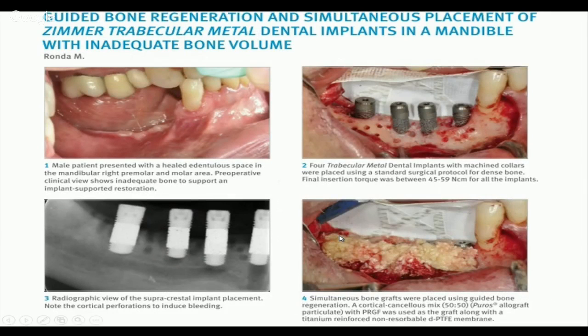the Regenerex. This is one of the examples, again by Zimmer, where they have introduced this kind of dental implant with about 0.5 to 1 millimeter of porous thickness, where porosity is about 70%, and this is more than enough to increase the surface area by about 90%, and eventually gives tissue ingrowth and biological fixation of the implant to the tissue site. And you can see from microCT that there is tissue ingrowth into the implants.